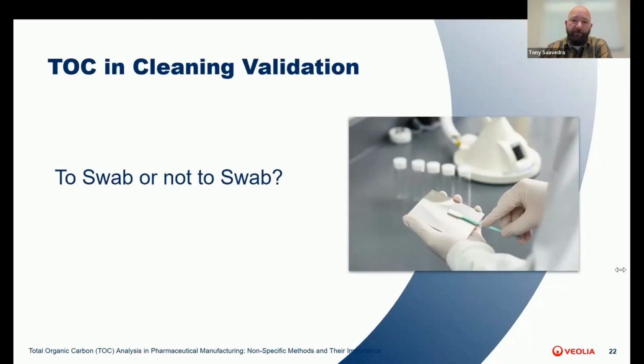This method is often sufficient when equipment is easily rinsed with smooth surfaces and simple angles. You may also use it if the contaminants are readily soluble in rinsing solution, and you can demonstrate that the rinse solution has contacted all of the surface of the equipment. It may also make sense to use this method if the equipment is too large or complex for comprehensive swab sampling to be practical. In many cases, a combination of both methods provides the most comprehensive validation. For example, you might use a final rinse for your routine monitoring with periodic swab sampling of critical areas.